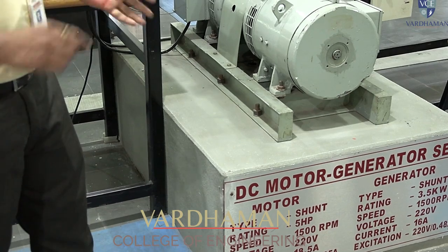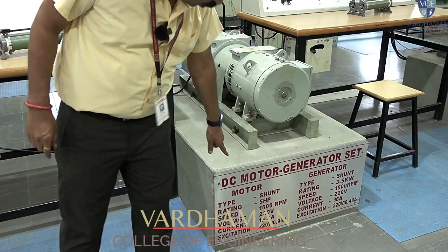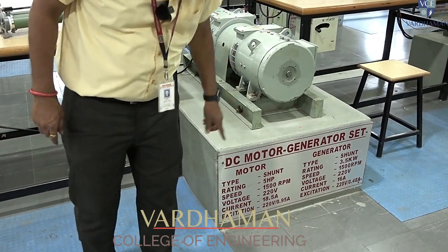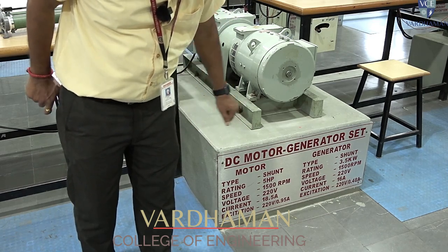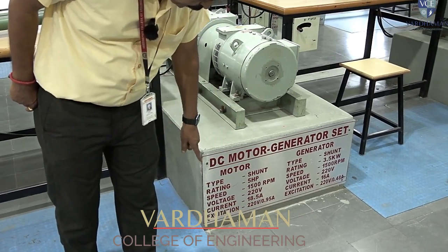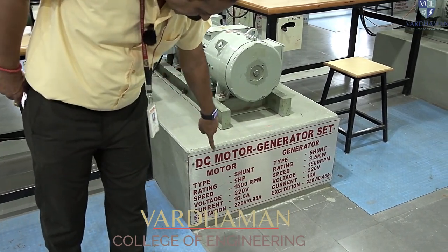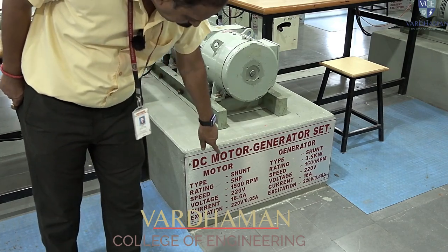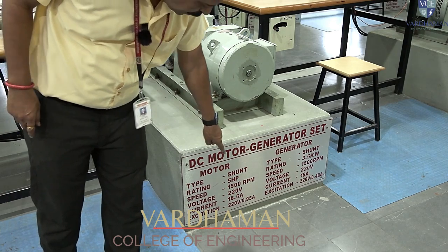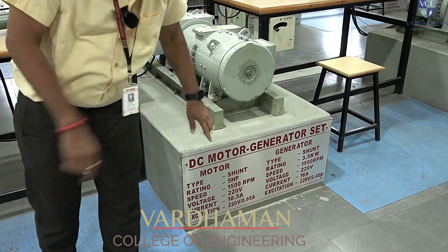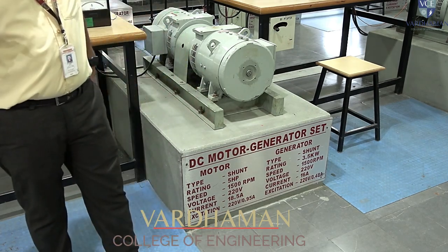Then only you can operate the resistance currents within the limits of this specification. So the motor, generally, is a shunt motor. Rating of the motor is 5 HP. Speed of the motor is 1500 RPM, revolutions per minute. Voltage is 220 volts. And the current rating of the load that can be applied on the motor, maximum current will be 18 amperes, 18.5 amperes. And the excitation current which is given to the motor side is 220 by 0.95. This is about motor specification. One should write these specifications under the circuit diagram in the manual.